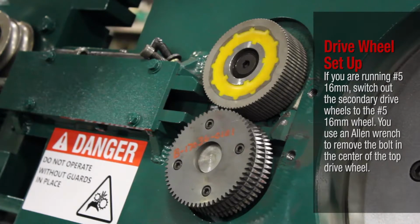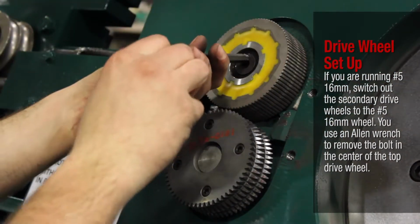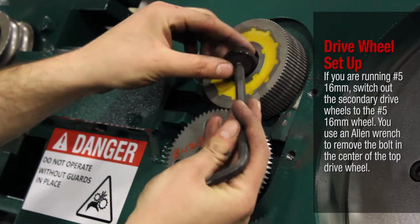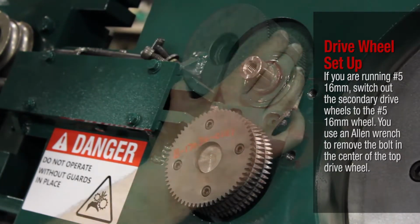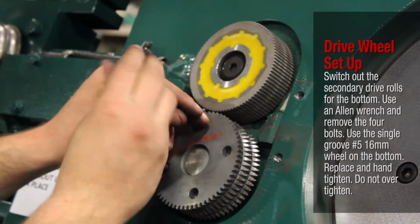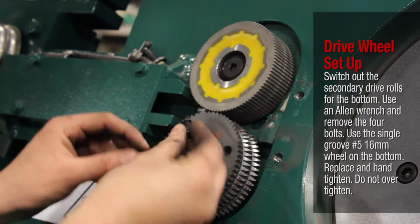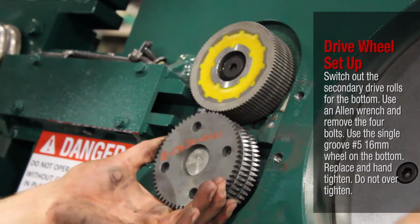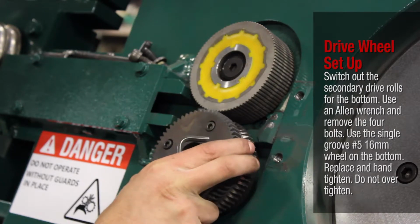Drive wheel setup. If you are running number 5 16mm, switch out the secondary drive wheels to the number 5 16mm wheel. You use an Allen wrench to remove the bolt in the center of the top drive wheel. Switch out the secondary drive rolls for the bottom. Use an Allen wrench and remove the 4 bolts. Use the single groove number 5 16mm wheel on the bottom. Replace and hand tighten. Do not over-tighten.